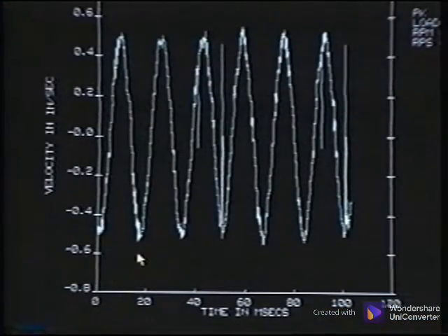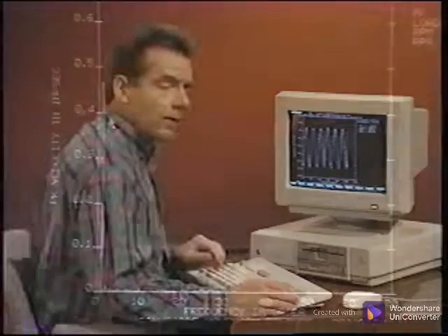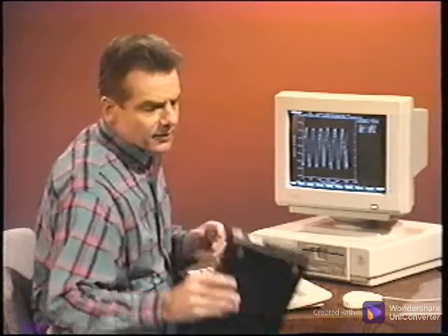Here we see a simple sinusoidal pattern at a frequency associated with a 1 times turning speed of the shaft. This velocity waveform is demonstrating significant unbalance on a fan and is very good information. But the velocity spectrum is similar, as expected. There is not much energy evident in the spectrum except unbalance. We're not able to change the unit's display of a singular time waveform after it has been collected. Instead, the data must be collected again using a different setup in the analyzer.